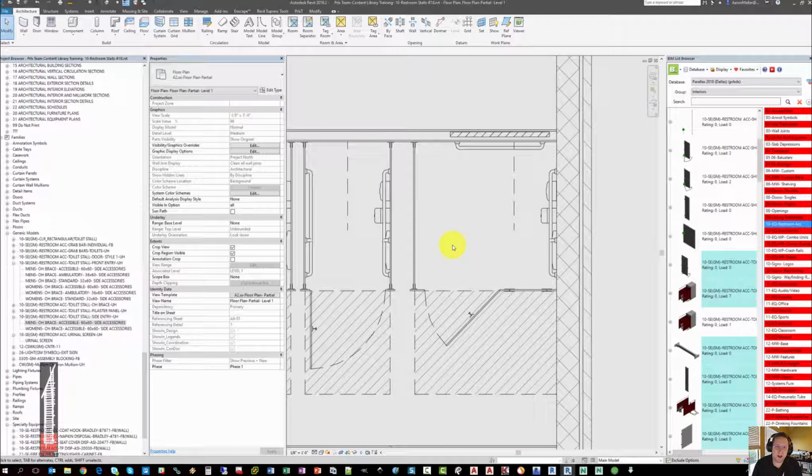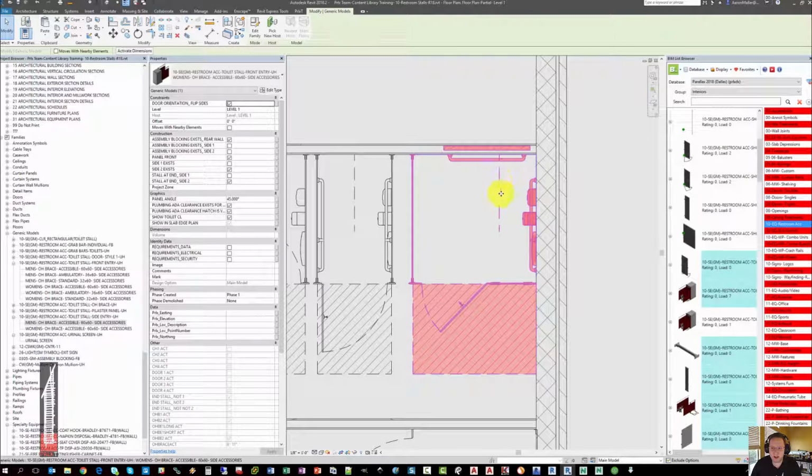Plumbing fixtures themselves are not included in the toilet stall library because toilets come in a variety of configurations, and some Revit toilets are wall-hosted, face-based, floor-hosted, and have other options. For instance, the Parallax toilets have shared nested swappable flush valves. Having the toilet component nested in another component makes using shared nested flush valves much more difficult. So, these stalls provide a center line to let you know where the toilet should go. If you don't wish to see the center line, there is a checkbox that you can turn off.